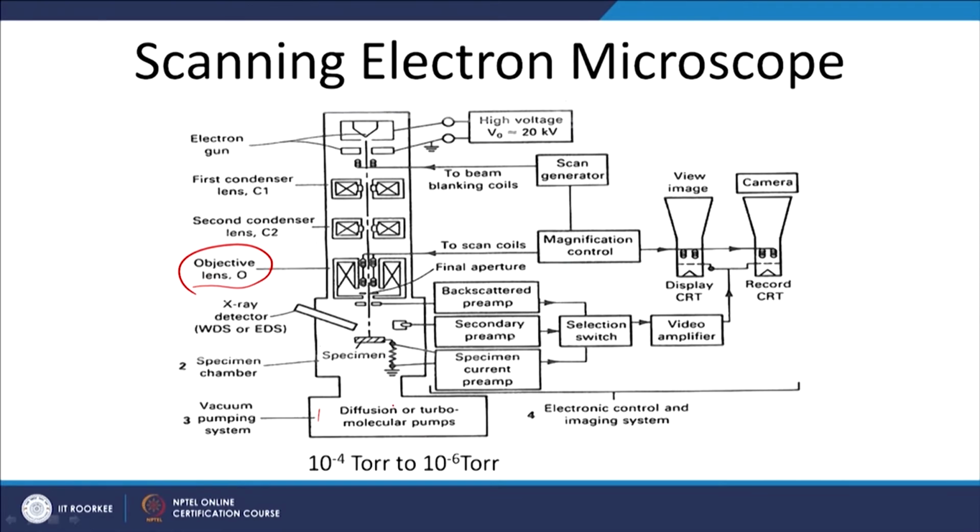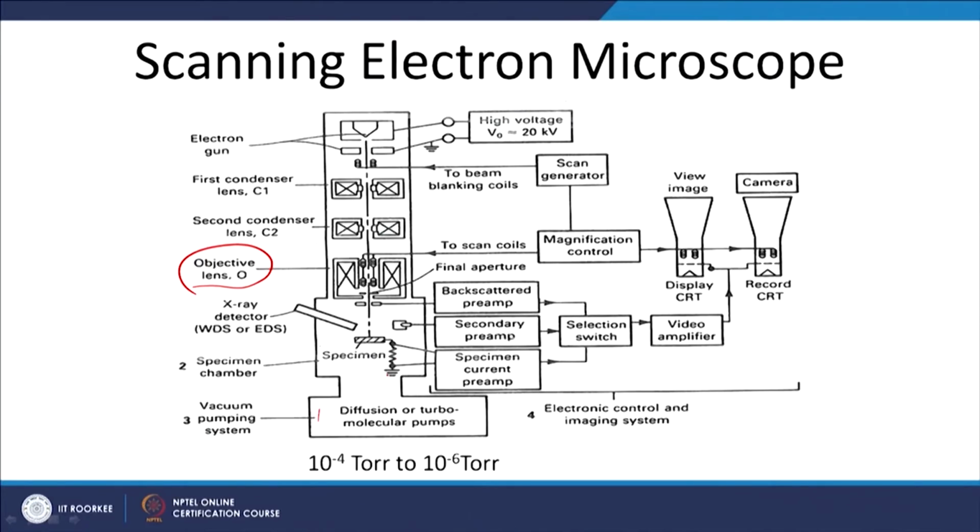We said that when we do the SEM we usually maintain a very high vacuum, right, because otherwise the electron would interact or scatter with other atomic layers. So, basically we have to make sure there is nothing else inside the chamber. Now, the detectors can be different things.